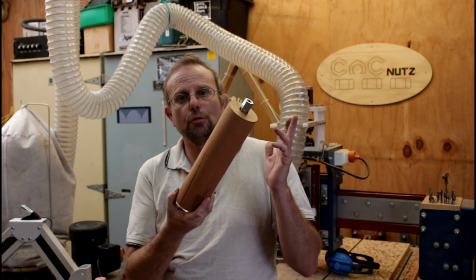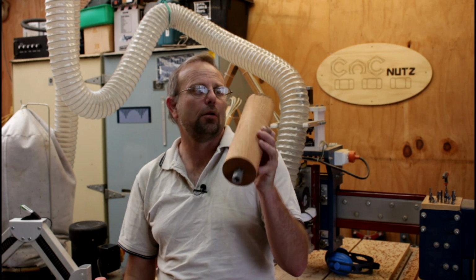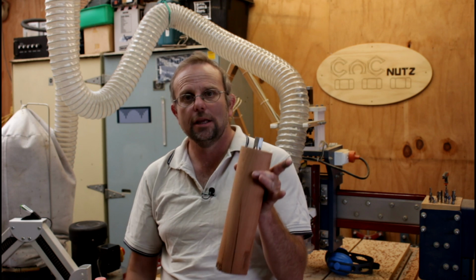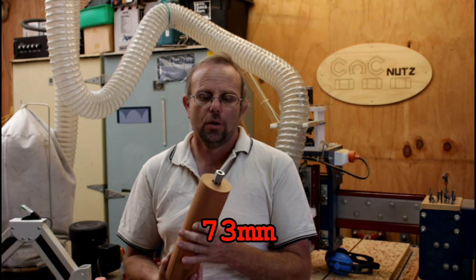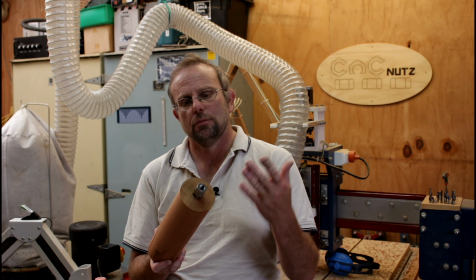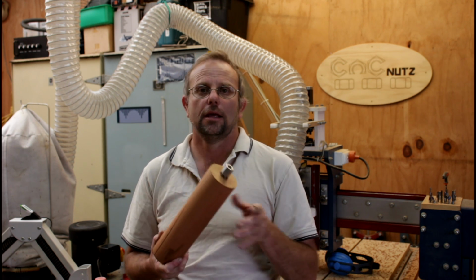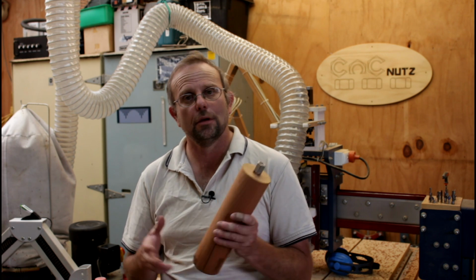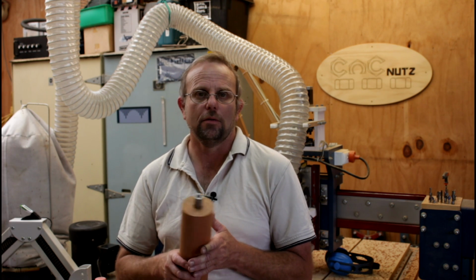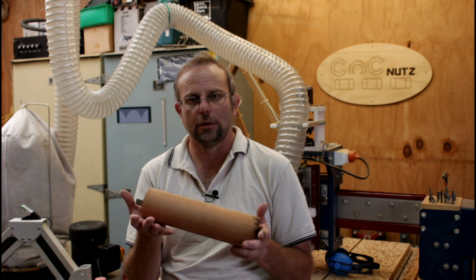I've now completed the rounding toolpath I created, and this is the finished result. The good news is, when I put the calipers on here, it measures 53 millimeters. Also, there are no flat spots on it when I rotate it, which means that I got the full 53 millimeter diameter cylinder out of my piece of stock. That means I don't need to go altering my file to any great extent to make it fit my stock.